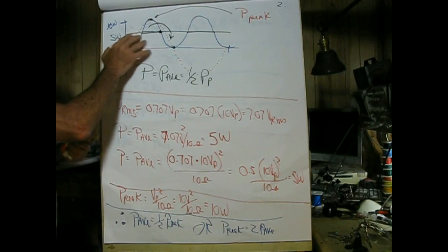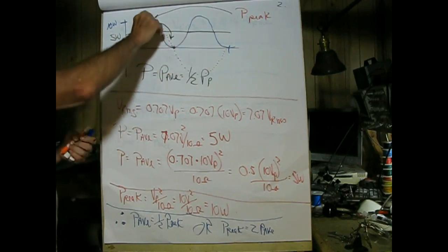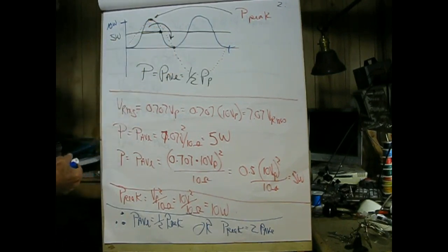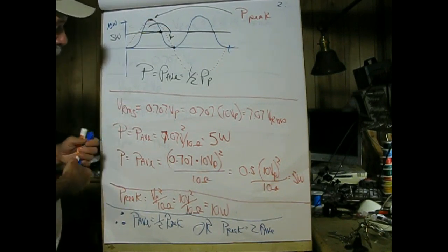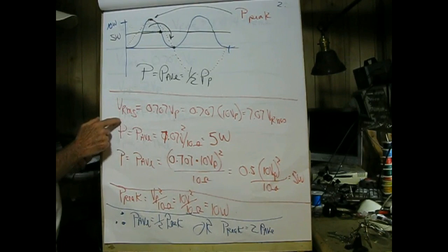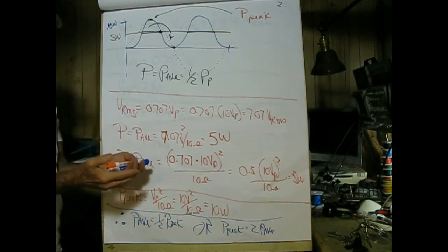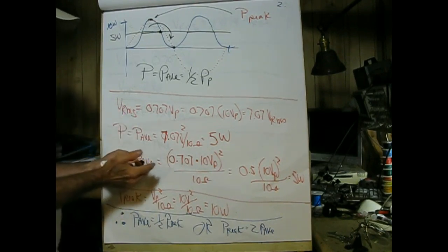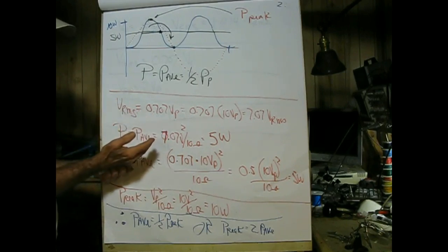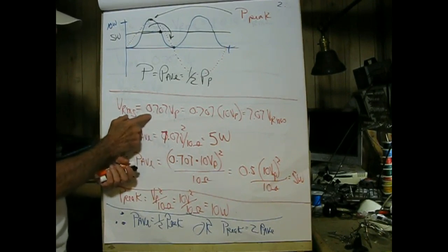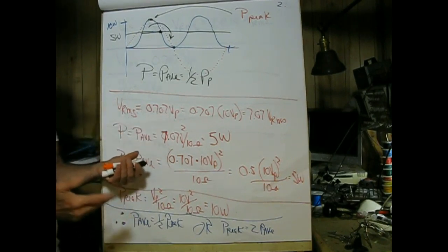So everybody, I hope, would kind of get the point here of rotating this, and it's, I think, a good graphic to show what is going on. The RMS voltage is the effective DC voltage which produces the same amount of heat in a resistor. And these experiments were done in the late 1800s. So the magic operator for this, which you must know, is 0.707 V peak, and this can be shown mathematically.